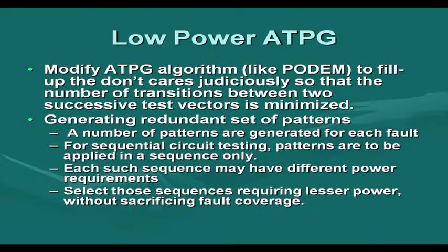So, what will happen is that many of these patterns have the capability to detect a number of faults. Though a pattern has been taken into the set because it could detect one particular fault, it has the potential to detect more faults. So, once we have a redundant set of patterns, we can choose patterns so that they consume less power. A number of patterns are generated for each fault depending upon that n detect principle.